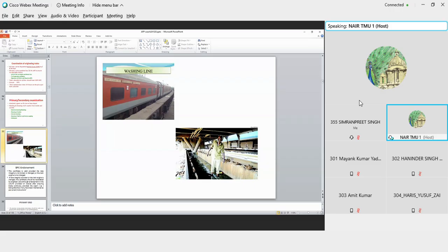And on the right hand corner, you see that the staff has started checking the undergear. The safety of the coach lies in the undergear. Anything above the undergear, in the superstructure, is nothing but cosmetics. The safety of the coach lies in undergear. So this gentleman at the bottom inside the pit is basically looking after the undergear equipment, whether the springs are intact, whether the brake blocks are intact, all the nut bolts are intact, and the auxiliary reservoirs or the control reservoirs are intact or not.